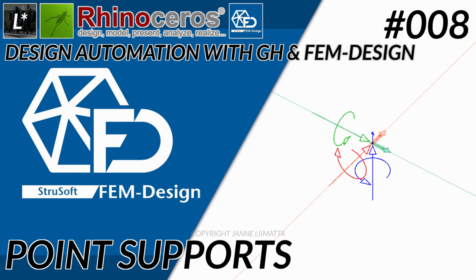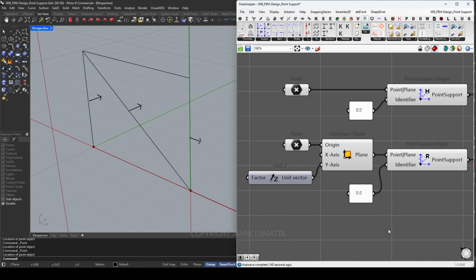Next thing to do is to create point supports for the frame. Easiest way to create supports is to use pointSupport.hinged or pointSupport.rigid components. You can either input a point or a plane. For the rigid supports plane, I have flipped a normal XY plane by inputting the world set vector to the y-axis of the plane component. We have also provided identifiers for the supports to imply the type of support they are.